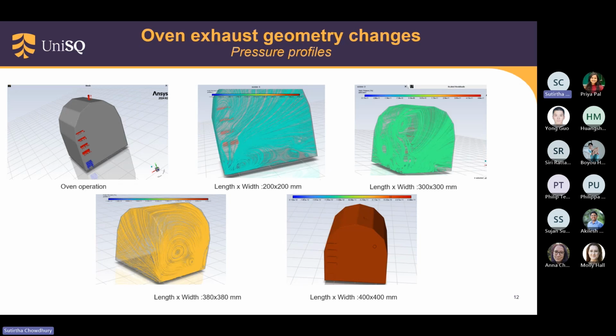Afterward, if we focus on the temperature profiles, it shows that though it has good temperature profiles, the pressure lies in the negative. Negative pressure is never considered good for a duct model or an oven structure, because with negative pressure there will be vibration, more turbulence, and no saturated temperature throughout the oven.